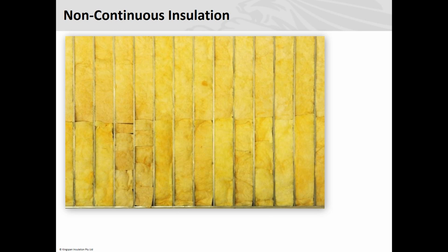In the commercial, there are some concessions now. If you have lighter coloured walls and roofs, you get some concessions, and they're taking those concessions out. For example, if you had a dark colour roof with a solar absorption above 0.4, versus a lighter colour like a zinc loom or a white roof, you've got a concession. They're taking those concessions away now. With lighting, if you were using LED lighting, you got a concession as far as your energy assessments go. Now they're assuming that everybody's going to be using LED lighting, so they're taking that concession out as well.